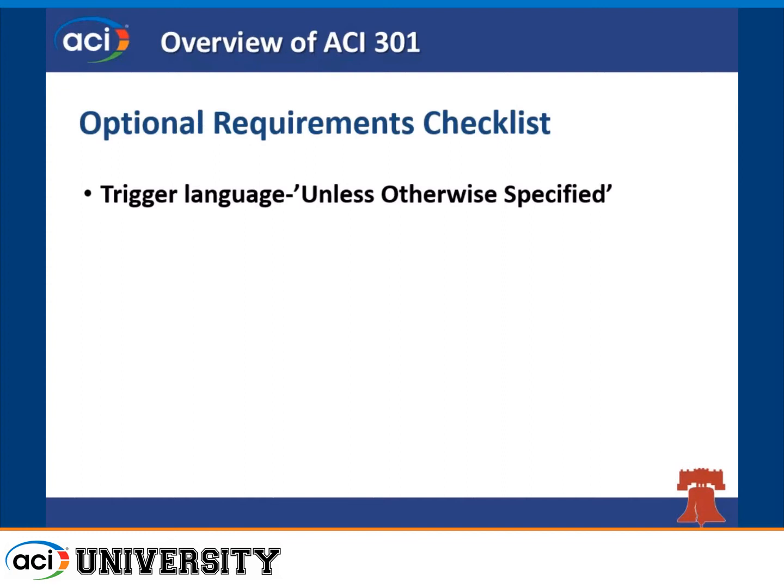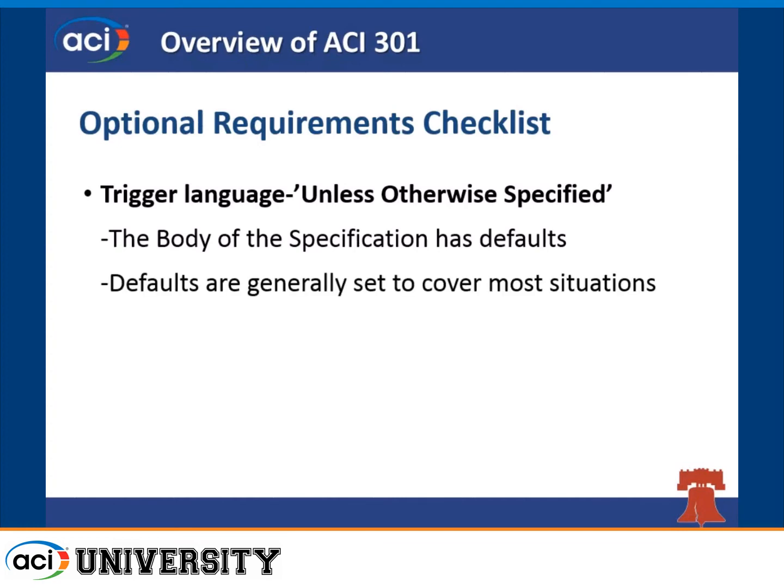Here's some things that you could change in this area, which we have defaults for, but you might want a different number, a different material, a different construction method. So the body of the specification has defaults. Back in the good old days, it had a default on slump of 4 inches. We no longer have that in the specification, but there might be one of you out there who cannot let go of that control and wants to put a default slump back in. Or we would rather that the contractor decides what that slump is at this time. But there are other examples out there.